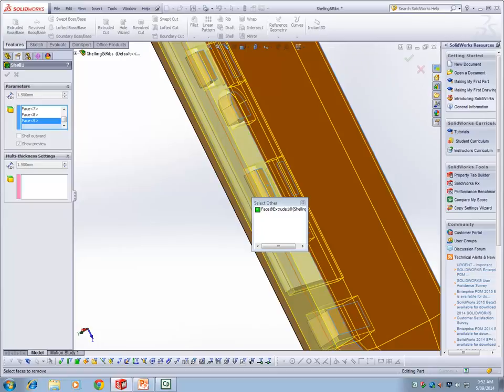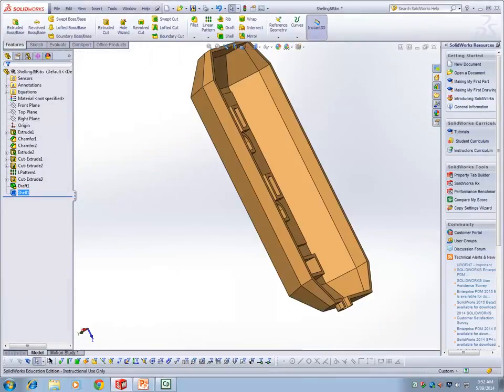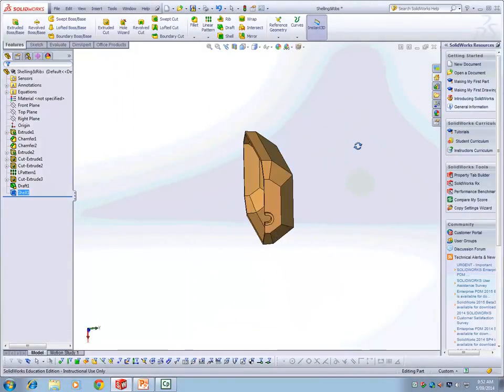When you actually go into an assemblies, it's very hard to look at the edges or faces or vertex points. So select other is a tool that will go inside into your part and show you the edges on the surface on this particular. Okay. So once this is done, you can say yes. So this is what you should have in the end with a shell.